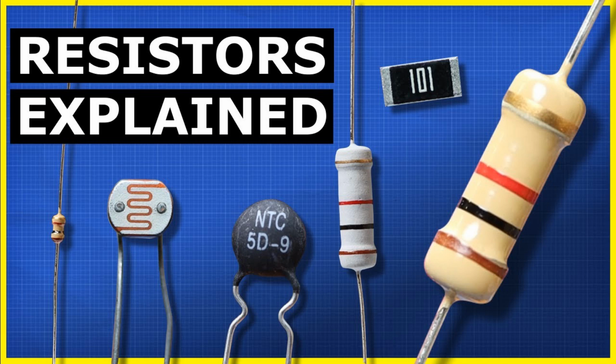Current noise is associated with the random fluctuations in the flow of electrical current through the resistor. It is directly related to voltage noise through Ohm's law, I equals V/R, where I is current, V is voltage, and R is resistance. Therefore, if the voltage noise is reduced, the current noise will also decrease. White noise: thermal noise is often referred to as white noise because its power spectral density is constant across a wide frequency range. In other words, it contains random fluctuations at all frequencies. White noise has a flat frequency response and is characterized by its RMS voltage or current amplitude.